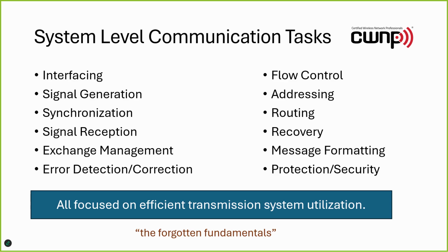So these are the concepts of synchronization, and this is done usually, in networking protocols, through some kind of start of frame delimiter, a preamble, whatever you want to call it, but some series of signal bits that are really just fixed waveforms, fixed signals that say to that receiver, this is not just noise. There's an incoming communication. And so you need to use this stuff that's not just noise to synchronize as a receiver so that you can do signal reception. And that's not something unique to wireless.